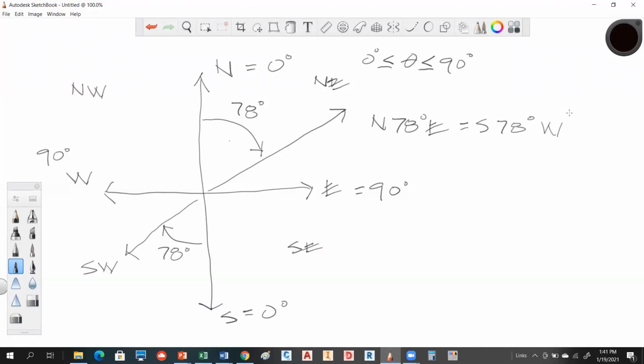So they're 180 apart in terms of the way they're facing, but it's just a straight line, okay? So this would be called the forward bearing. This is referred to as the back bearing, okay? Now, we're gonna deal with some calculations associated with bearings. That's a pretty important concept for any layout person to understand, which we'll be utilizing. So we'll see how that works. Again, I'm gonna spend a lot of time on Thursday with this.